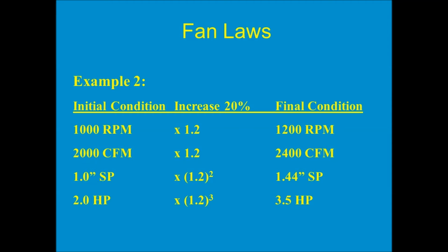73%. And so what we have to say to this restaurant owner is, well, hold on a minute, the fan laws are not going to let us do that, because even though you only want to increase the speed of the fan 20%, it's going to require much more horsepower, and unfortunately, the fan you installed only has a 2 horsepower motor. So you need a bigger motor.